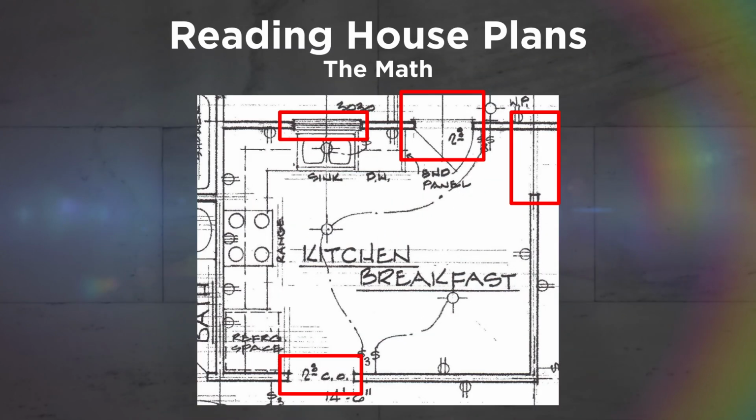Very important. In the kitchen, the person who drafted this plan has a 30 by 30 inch window or 36 by 36. Very typical for many kitchens. Once your finished plan is drawn, the window space including trim would be somewhere between 40.5 and 42 inches, depending on the trim size. The 3 remaining openings include a door to the exterior, which is 2'8", a cased opening on the bottom, which is also 2'8", and the third opening into the dining room is simply the space between the end of a wall and the inside of an exterior wall. That dimension scaled out to be approximately 36 inches.